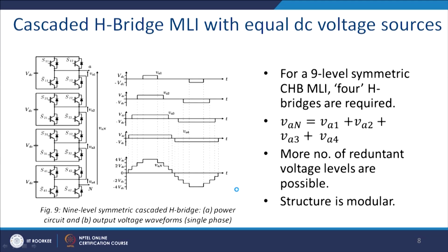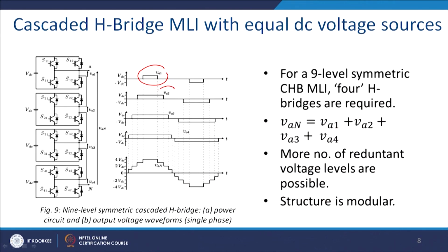So, see that this is the application of the 9 level multi-level inverter, and it is simple to realize. You have 4 blocks, so 2k plus 1 is 9 level. Essentially you can switch it on like that, VA1, VA2, VA3, VA4, you add them in series and ultimately you get a wave very close to the sine wave.